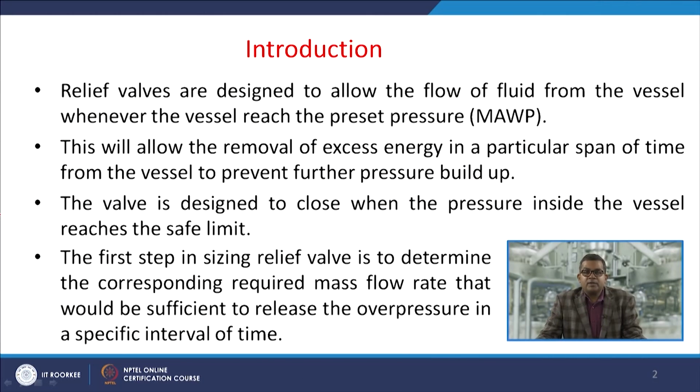Now basically relief valves are designed to allow the flow of fluid from the vessel whenever the vessel reaches the preset pressure, that is MAWP, the maximum allowable working pressure, which we have discussed already. This allows the removal of excess energy in a particular span of time from the vessel to prevent further pressure buildup. Usually the valves are designed to close when the pressure inside the vessel reaches the safe limit. So we already have the set pressures, etc.